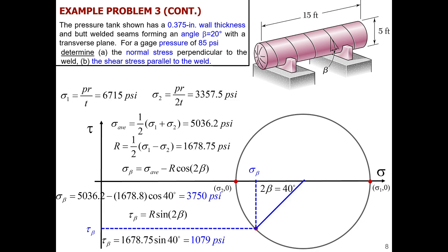Ideally at this point we would use these values of the stresses and ask ourselves whether the particular welding technology produces a weld of good properties, so that we can allow these stresses to develop and there will be no failure or some crack that will initiate here and then may lead to failure. So these are important numbers for this type of design.